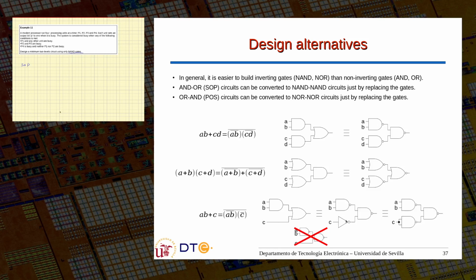If in doubt, just double complement the expression and obtain the expression with the NAND in this case, and you will see that the literal that was alone here needs to be complemented now. But most of the time you don't really need to make the calculation. Just use your sum of products and go directly to a NAND implementation.